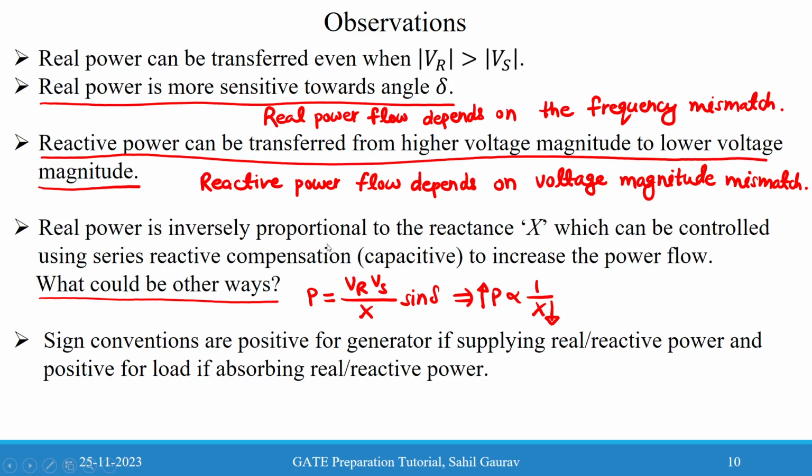No, here we have seen that if you want to increase the real power flow in the transmission line, then you have to decrease the reactance of the transmission line. Sir, delta also changes, sir. Delta.